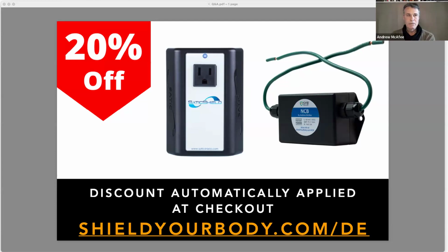That's correct. The wired version blocks foreign current that's coming from a well or anything else touching the earth. Even though the breakers are off, there's still current coming in. So I needed the NCB Pro, the wired version, to stop that current coming in on the grounding conductor from the secondary earth reference.